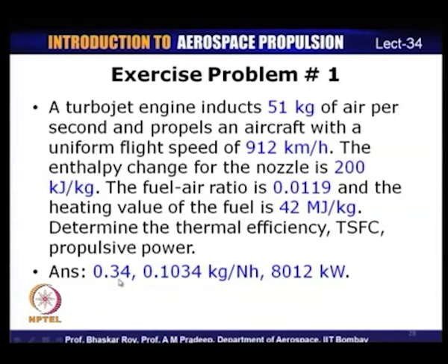Determine the thermal efficiency, the fuel consumption and the propulsive power. So, answer for this is thermal efficiency is 0.34, the fuel consumption is 0.1034 kilograms per Newton hour and the propulsive power is 8012 kilowatts.